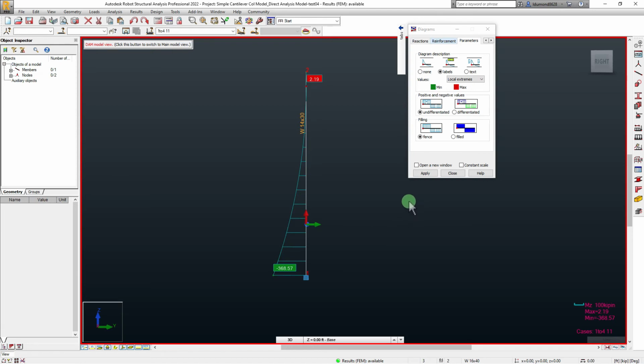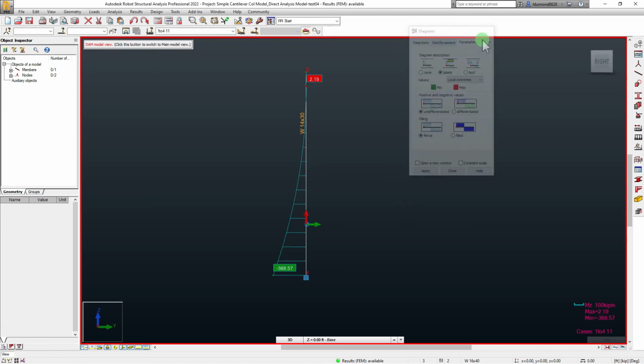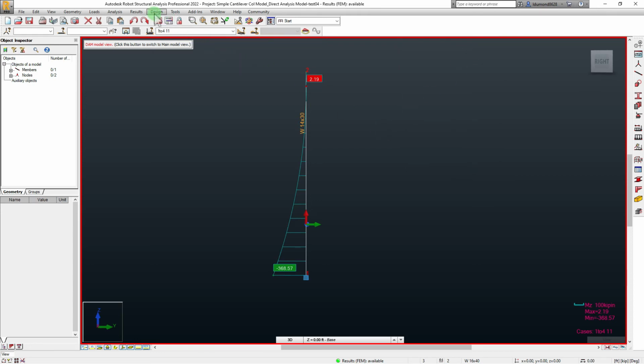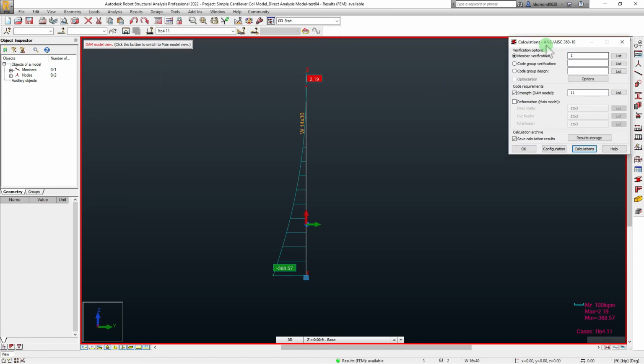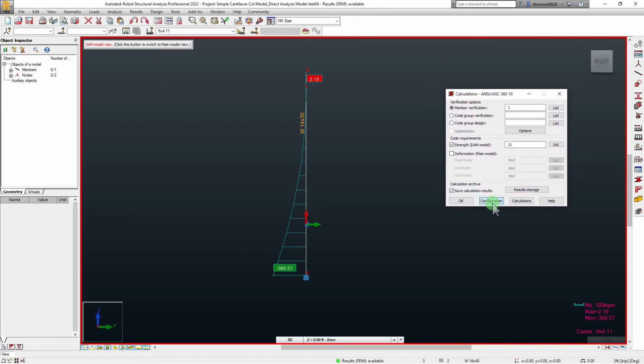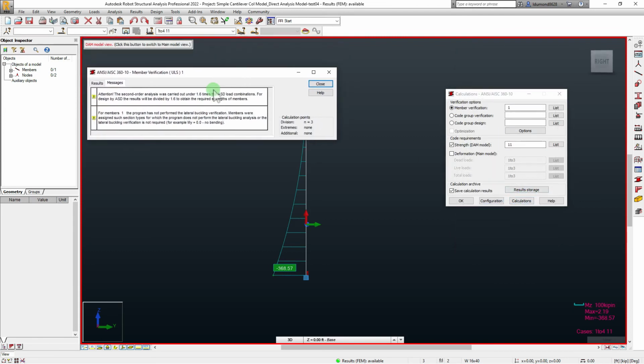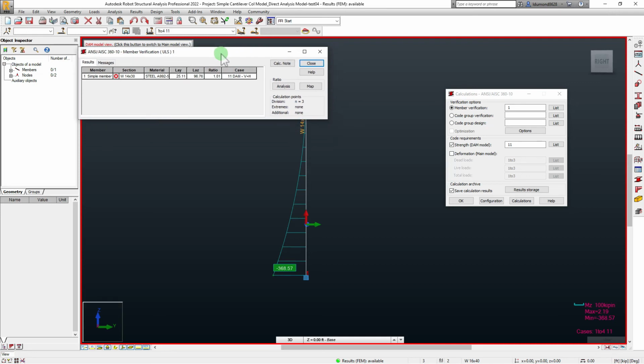Okay, so you can see how do I know this basically, right? How does an engineer know that for a fact? So keep in mind this is like 370 kip inches. When I go to my design results, I can take a shortcut and not have to switch by pulling up our calculations tab directly and making sure my settings are right and hitting calculations. This warning is what's related to this value right here. You come over here and you'll take a look at it.